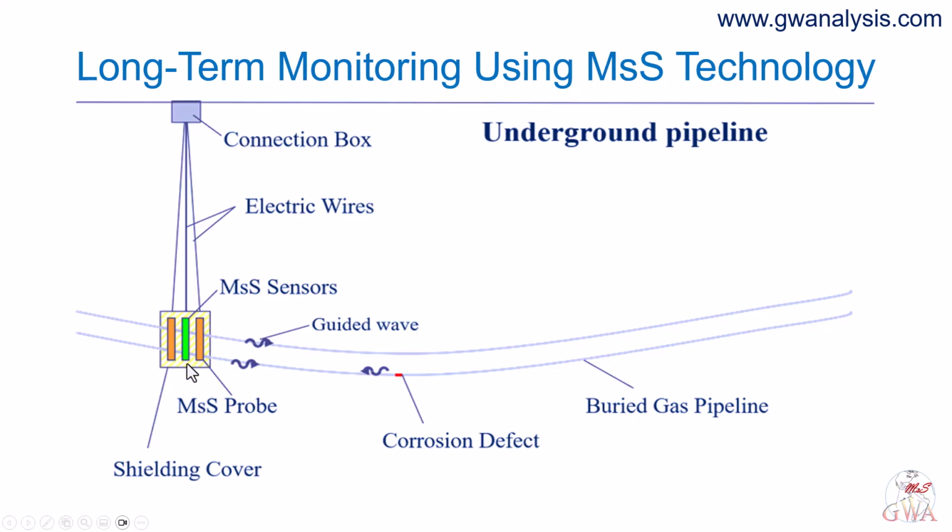Now the important part, and this is the reason monitoring is worth doing. In a single inspection, you compare a signal against the background noise in that record. A defect has to stand above the noise to be called, and we have said that means a signal-to-noise ratio of about 2:1. In monitoring, we compare today's signal against the same probe in the same position measured last year. The pipe features, the welds, the supports, the corroding all produce the same signal they produced before, and they subtract out. What is left is the change.